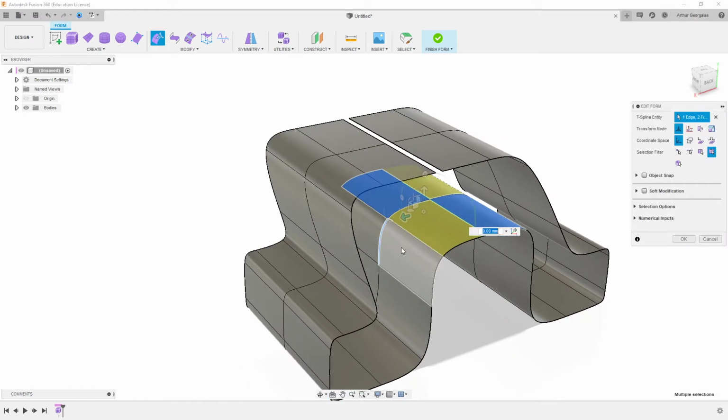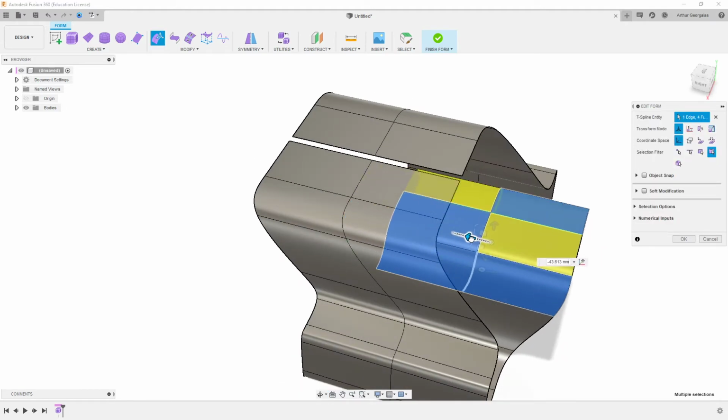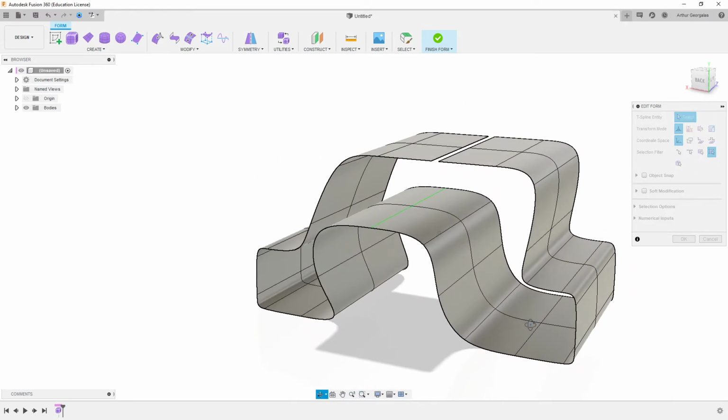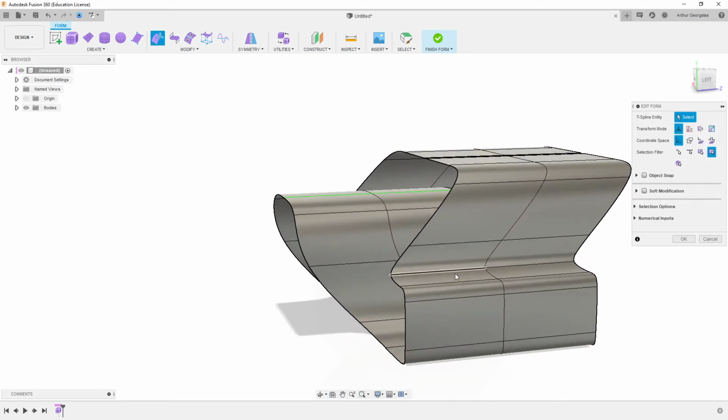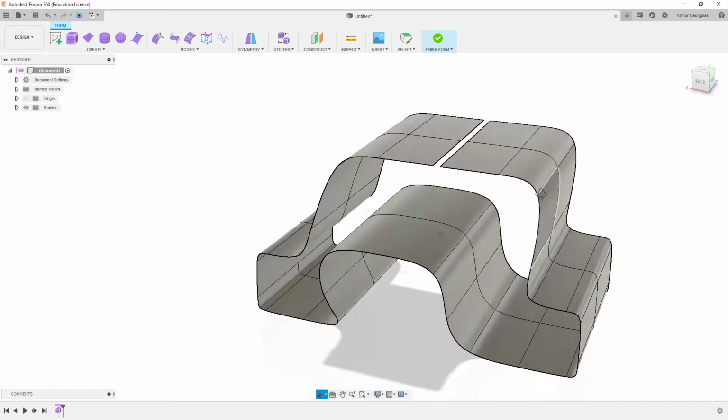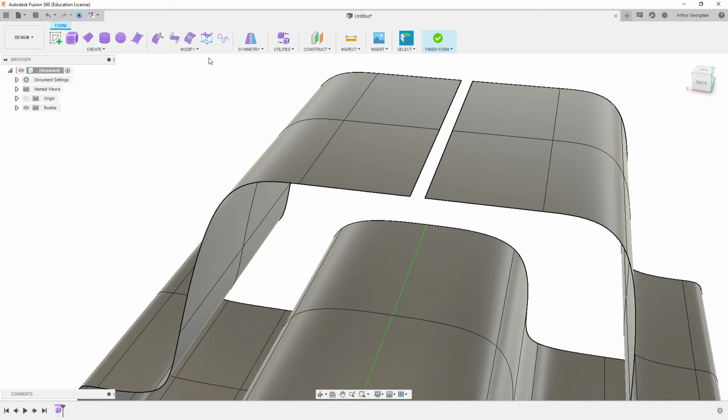I hope you can see why I would suggest that you model with a bit of purpose, because it's really easy to make things that are unnecessarily complex and actually come up looking just messy. One thing we want to do here is probably use the merge edge command. What this allows us to do is select an edge here and here, select our second set of edges like that, and that's going to bring them together.